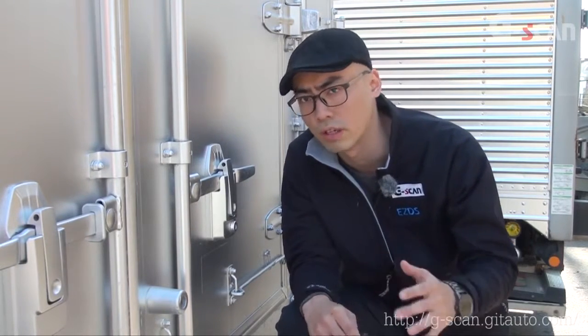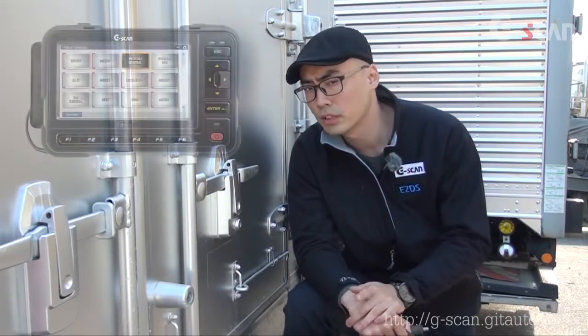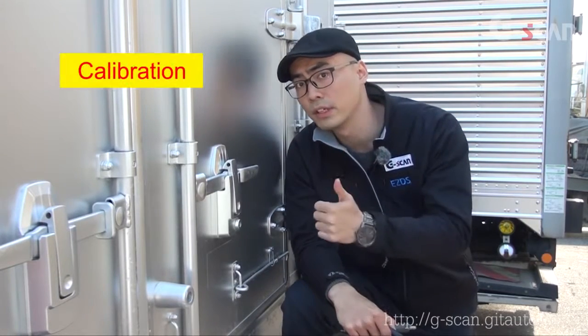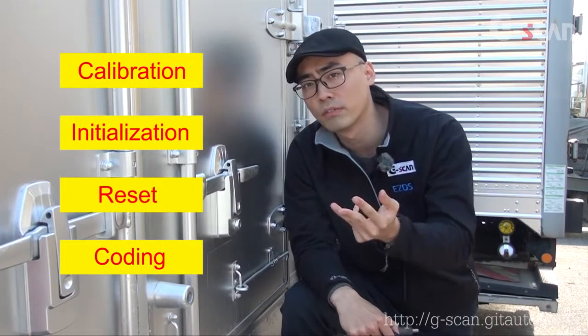From the mid-2000s, almost all vehicles are equipped with a bunch of electronics, such as computer modules, solenoids, and sensors. For the purpose of achieving advanced comfort or outstanding performance, engine computer units started to save or learn data from the operator's driving habits. Inevitably, the importance of computer control has been increasing. Whenever you perform repairs on most recent systems, even simple replacement of sensors, you must use a scan tool to reset or erase learned data in the ECU. Other than erasing and learning functions, there are calibration, initialization, reset, and coding functions.